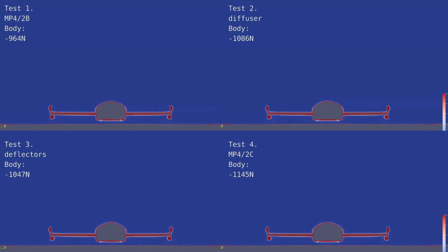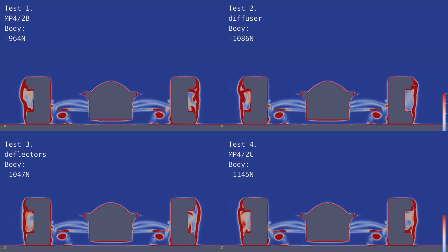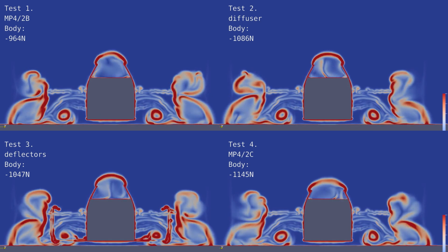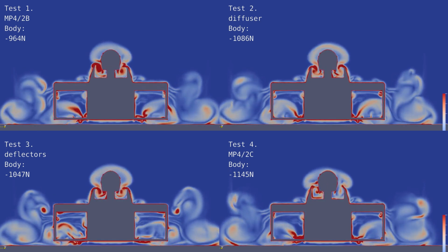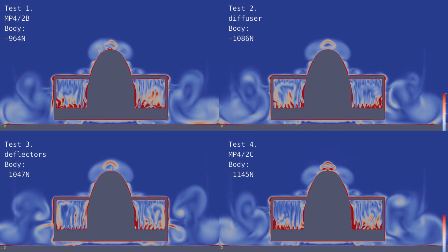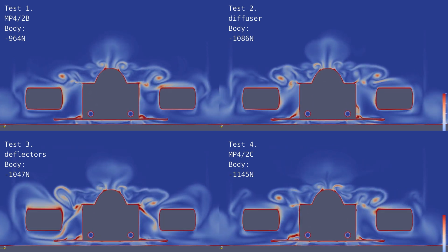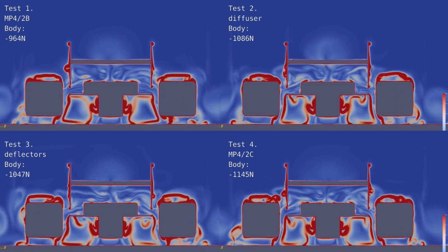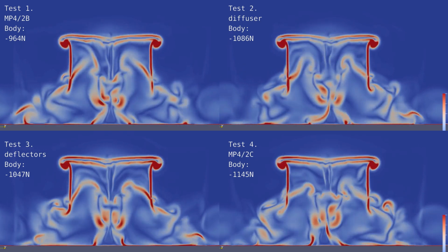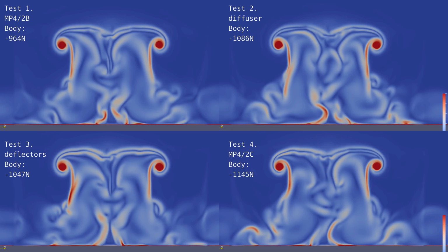The Vorticity X movie is supposed to show the differences in the vortex flow structures. The problem is that there isn't much difference again. The expected difference from the Test 3 deflector doesn't change the amount of rotating air that enters the radiator. The vortex core is pulled outwards of the side pods instead of impacting it. However, there's still rotating air entering the side pods.